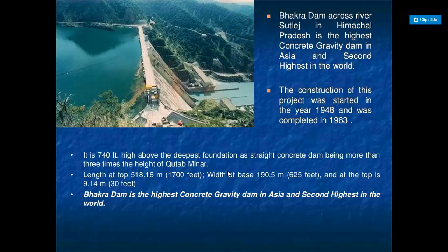These forces are divided into two categories. A, forces such as the dam weight and water pressure, which are directly calculable from the unit weights of the materials and the properties of fluid pressures. And B, forces such as uplift, earthquake loads, silt pressure, and ice pressure, which are to be assumed with a varying degree of reliability in estimation. For the second category of forces, special care has to be taken and reliance has to be placed on the available data, experience and judgment. It is convenient to compute all the forces per unit length of the dam.